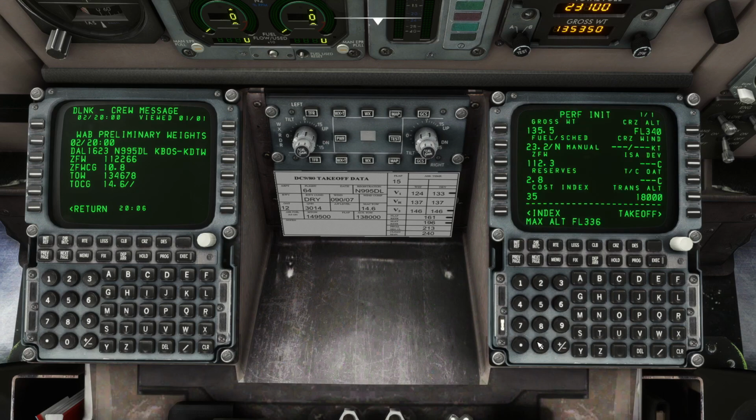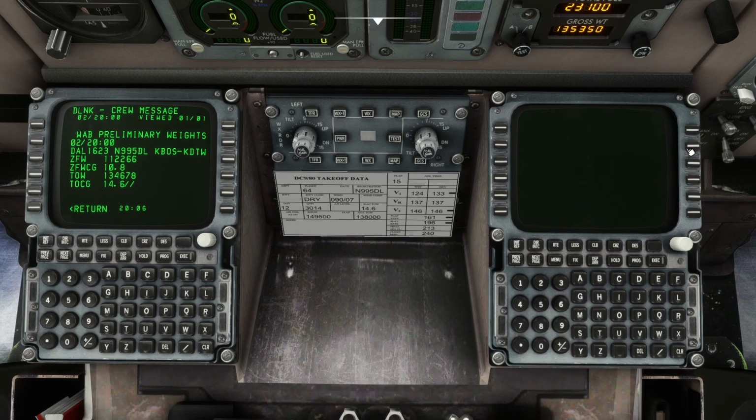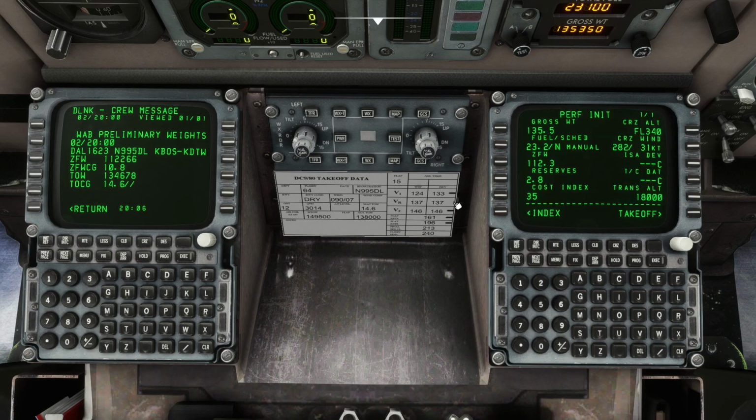With the cruise winds 282831, I usually ignore that, because if it's a difference of 400 feet, that difference will easily be made up burning fuel in the taxi and takeoff. Only if it's like 1,000 feet or more do I really begin to take that into consideration. So that's that filled out. Now it's on to the takeoff performance.